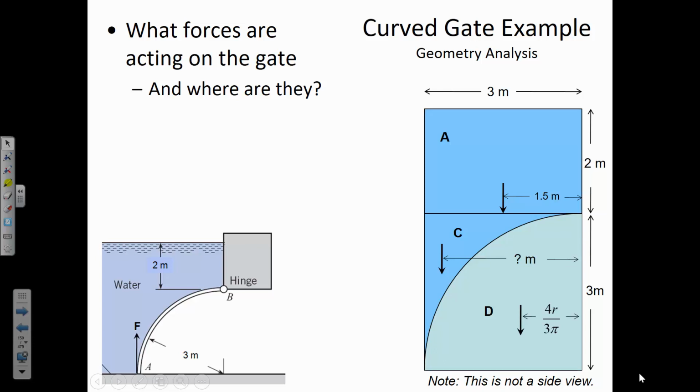All right, so the vertical force location. Basically, what I'm going to do is show you a couple of hints and then pause the recording, give you some time to calculate the actual numbers behind it. So the vertical force location, we're going to say that the two components are the quarter circle and this element C. And if you add those two things together is where you get B. And the overall element B is in the middle. The resultant force location is in the middle. So if we add the two components together, it should end up with whatever B is.